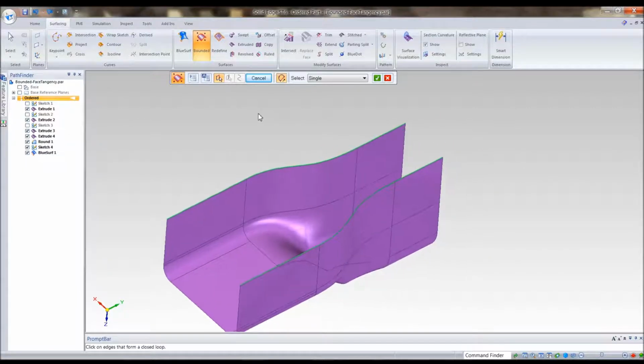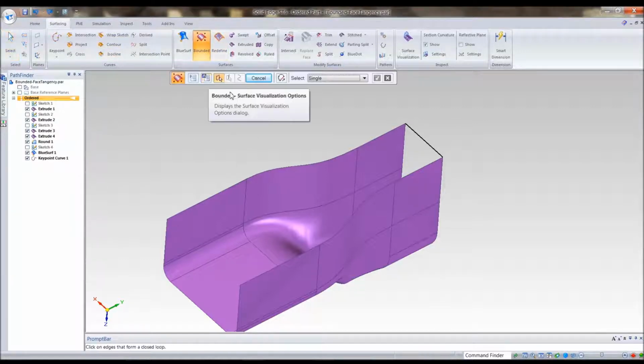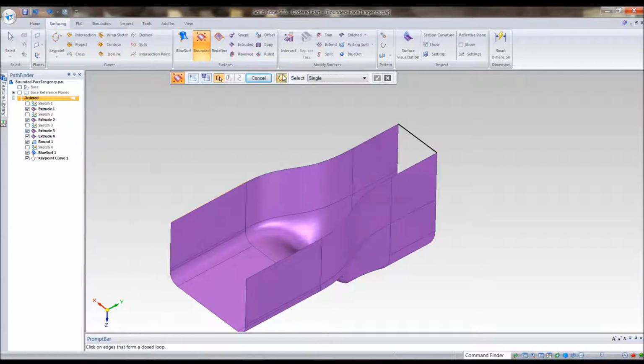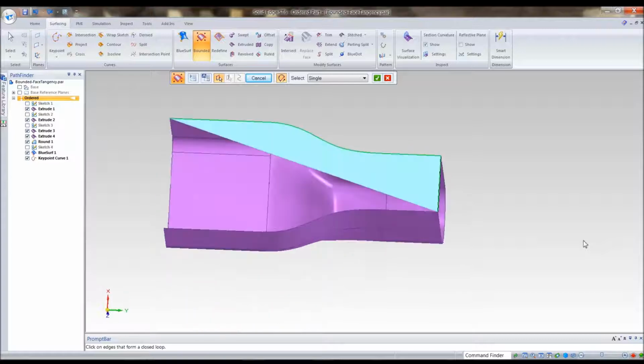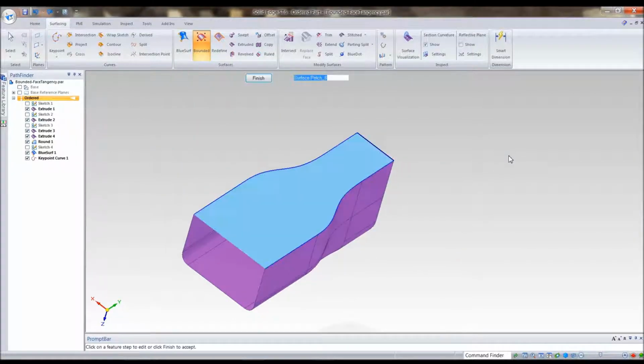I was thinking that this would close up, but I guess it doesn't really know where to close it. Let me pull this back. There, we'll pull back one of these key point curves and we'll do this again. So I guess it does need at least one of these guys. But again, I'm going to turn on the close curve, and as I go across these, there you see it's starting to fill in the surface as I click on these edges. And once I get here, it doesn't even need that one because it knows I want to close across there.